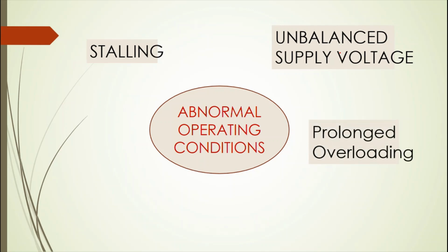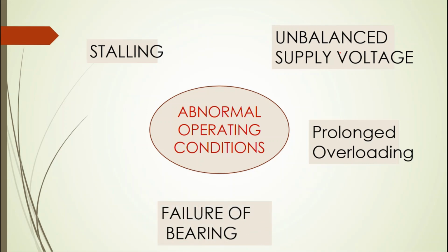Overloading. Prolonged overloading means we are overloading our motor for a long period of time, which may lead to temperature rise in winding and deterioration of insulation. Failure of bearing. This causes locking of rotor, and thus the bearing should be replaced and the motor should be disconnected.